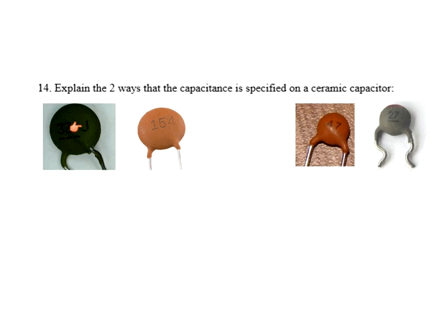Sometimes this letter over here is a K, which makes you kind of confused about it, because with K you think kilo. No, these letters are just tolerance when you see them. Ignore the letters. Look for the 3 numbers. That's all that you're trying to find.